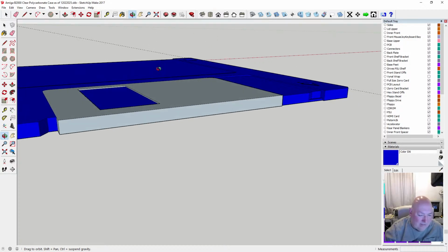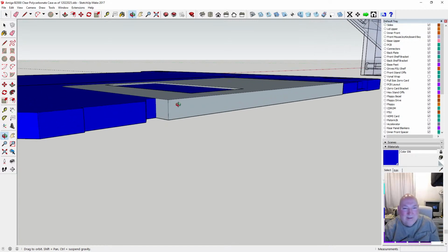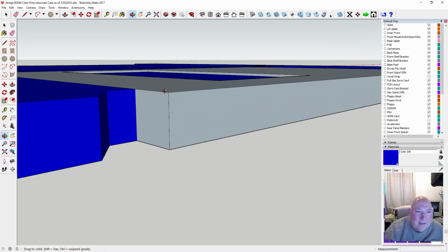I've got a floppy disk. So doing it from a disk, measuring a real disk. Oh, that's hollow there. It's got to be hollow. So what I'll do is go down about 0.25 of a mil. Up 0.25 of a mil and in 0.25 of a mil.